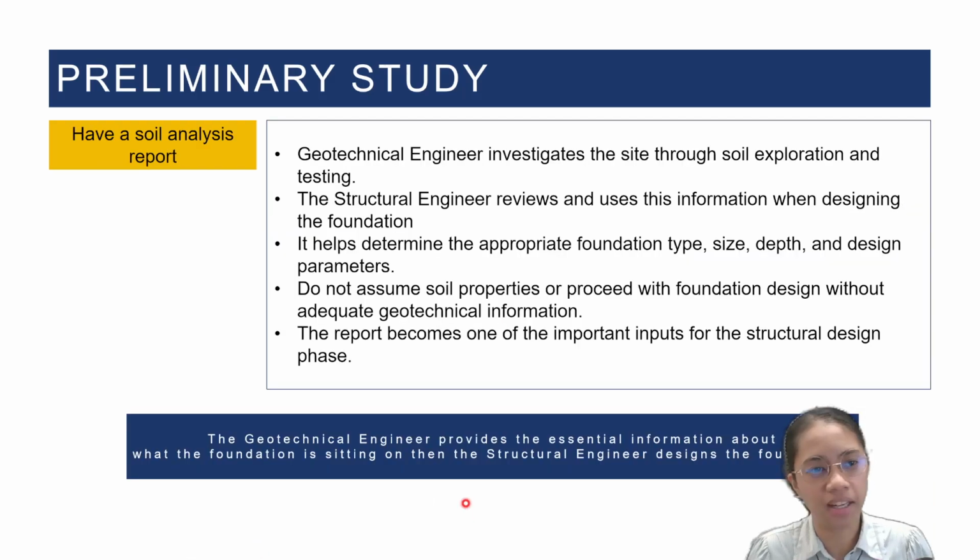Another one for the preliminary study is to have a soil analysis report. As you can read from here, the geotechnical engineer is the one who will investigate the site through soil exploration and testing, while the structural engineer will review and use the information that the geotechnical engineer gave through the soil analysis report when designing the foundation. Do not assume soil properties as a structural engineer or proceed with foundation design without adequate geotechnical information. Why? Because if you proceed with structural design without any information about the soil profile,